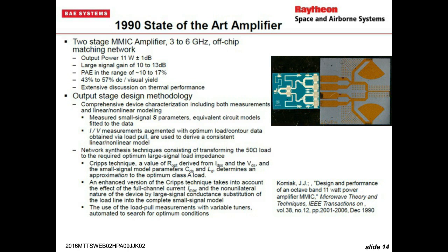I took it another step and actually put that ROPT substitution right into the small signal model in the design of the power amplifier, so I could jump back and forth between quasi-large signal and small signal. And at the time, all we had was load pull measurements, which used automated manual tuners, and that gave us optimum load information as a sanity check.